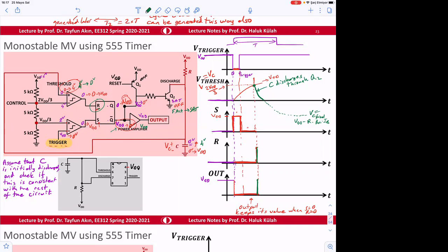through R, where Q2 is in forward active initially, forward active till VC becomes 0.2 volt or 0 volt. Or maybe I should write it formally, becomes V collector emitter SAT voltage, which is 0.2 or 0 volt.